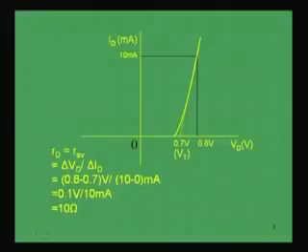So, at one operating point, if we know the voltage, say it is 0.8 volt and the current is 10 milliampere, which can be known easily if we see the data sheet of the particular diode that we are using. And the other point obviously can be taken as the point where the voltage is 0.7 volt and the current is 0. This is just the threshold point after which the current rises.